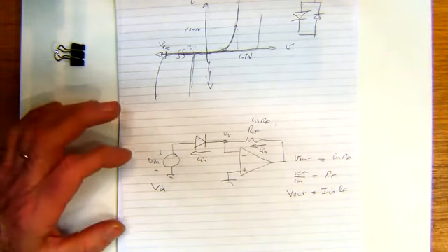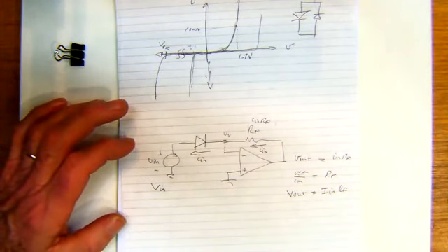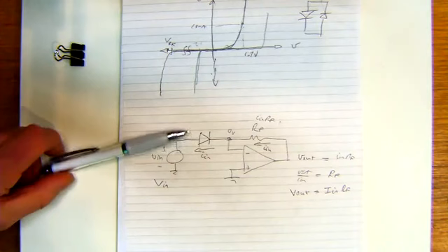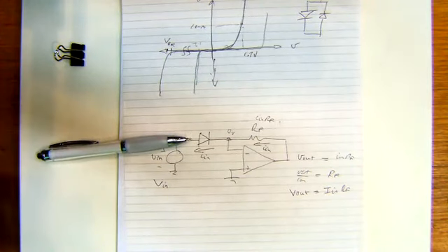That DC current can be provided if we make V in a DC value. So in actual fact we can reverse bias this diode, and it might be a photodiode. And if we reverse bias the diode, what happens to the depletion region in a reverse bias diode? Do you remember from this morning? It actually gets wider, doesn't it?